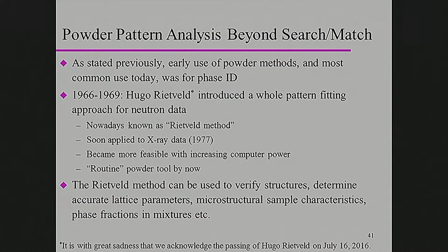You can use it to verify structures, get accurate lattice parameters, look at microstructural sample characteristics, phase fractions, and all kinds of things. One thing I would like to mention at this point is Hugo Rietveld actually passed away 2 weeks ago. Okay, some of you may already know that. So it's the 50th birthday of the Rietveld method, the 100th birthday of powder diffraction. It's kind of sad that he couldn't quite make all the celebrations that are planned this year.